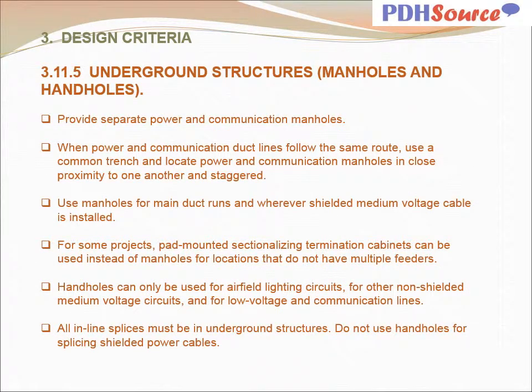For underground structures, manholes and handholds as examples, provide separate power and communication manholes. When power and communication ducts follow the same route, use a common trench and locate power and communication manholes in close proximity to one another and staggered. Use manholes for main duct runs and wherever shielded medium voltage cable is installed.